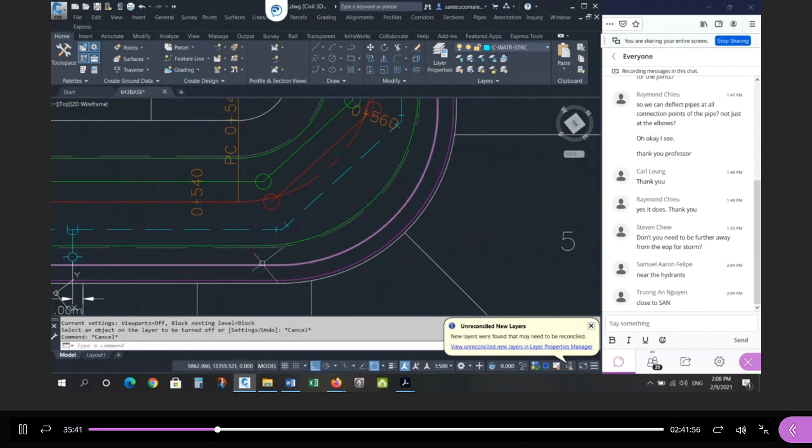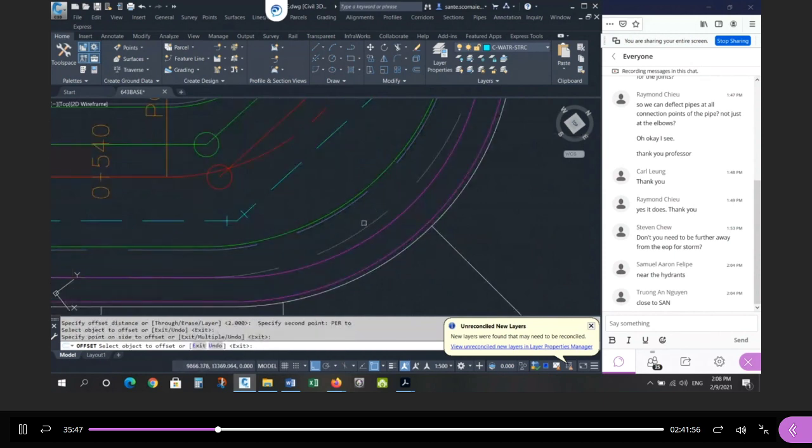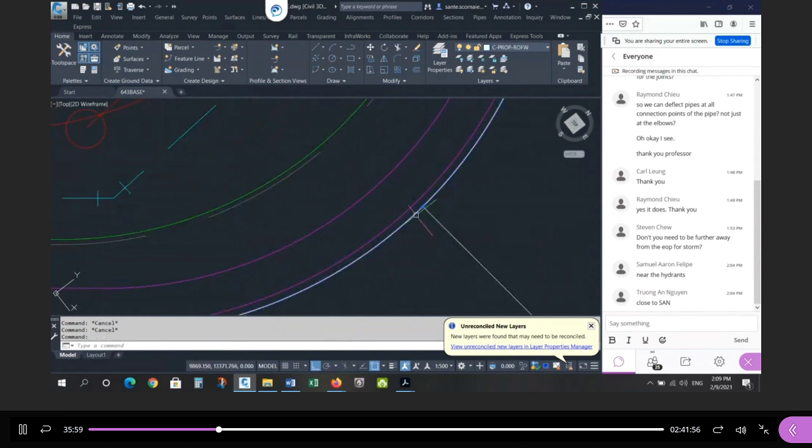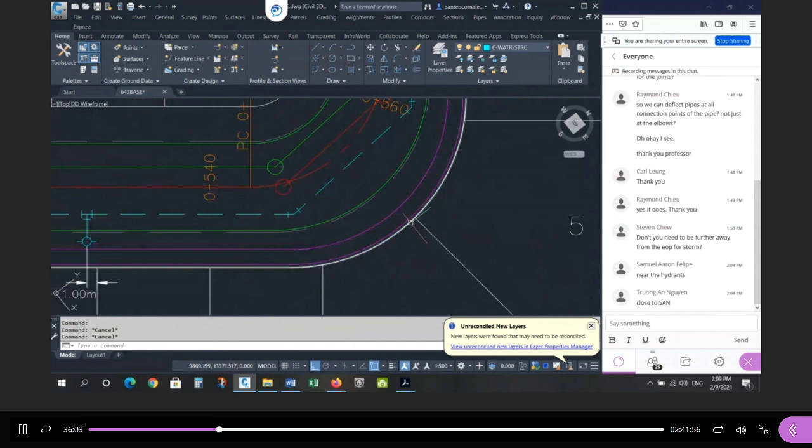If I offset from the back of curb, right? If I have from here perpendicular to the edge of the sidewalk, if I offset the back of curb, the sidewalk is there, and then 1.5, the sidewalk is there. So is the sidewalk here so that it has a constant offset from the back of curb? Or is the sidewalk here where the sidewalk has a constant offset from the right-of-way line? Remember the 0.3 meters between these two?